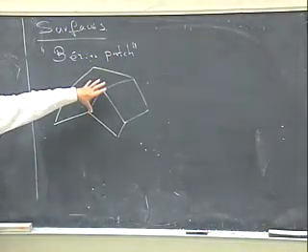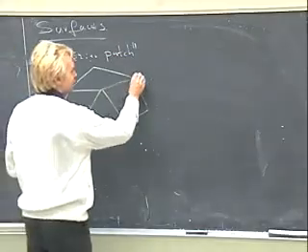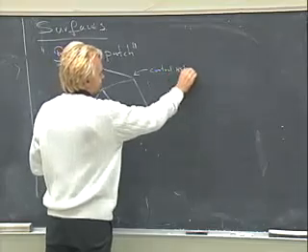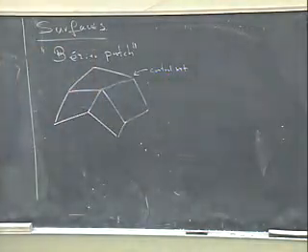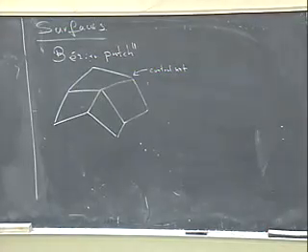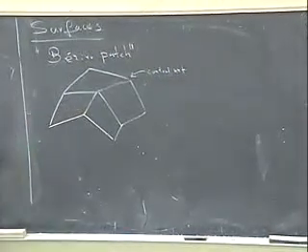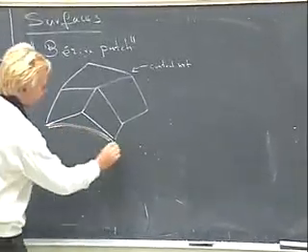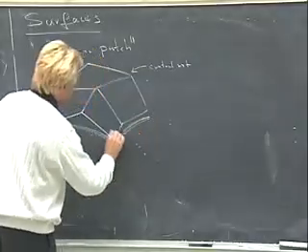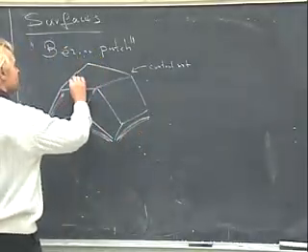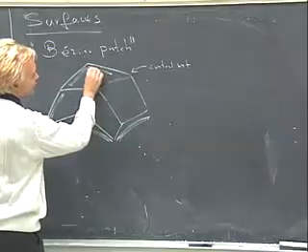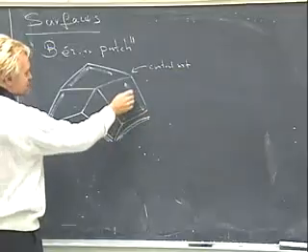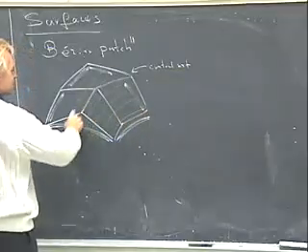And this control polygon or control net is a two-dimensional structure, right? From a polyline to a polygonal representation, we get a patch that is implied by this shape. And when you actually do the mathematics and you evaluate this thing, we talk about this later, you will get a smooth shape lying under this net, control net. Okay, so there's all these lines on this underlying patch.